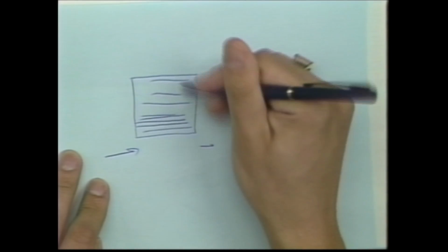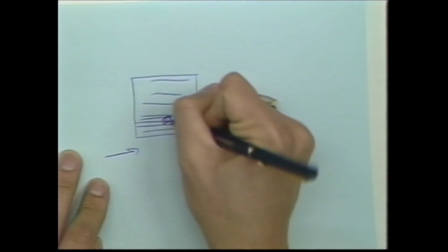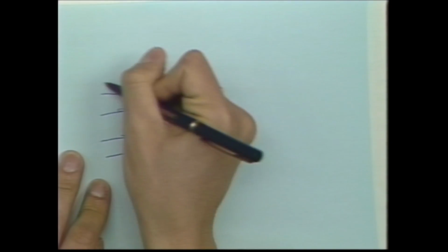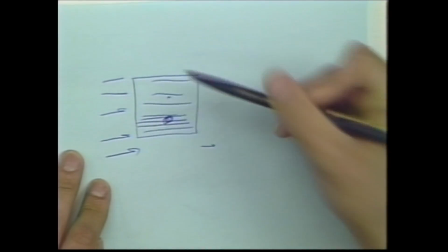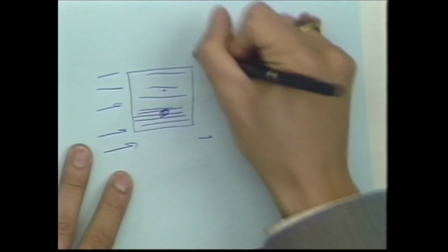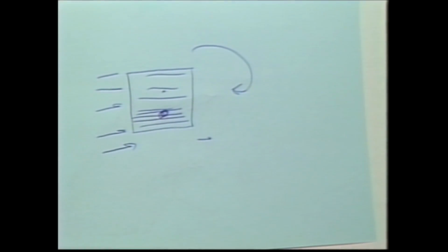Well, where is the center of mass of this element? It's going to be down here. Where is the center of pressure? Well, if the pressure is uniform, then it's going to be somewhere higher, somewhere up here. Well, what happens if you push on an element with a uniform pressure and the center of mass is down here? The element is going to rotate. You're going to induce vorticity.